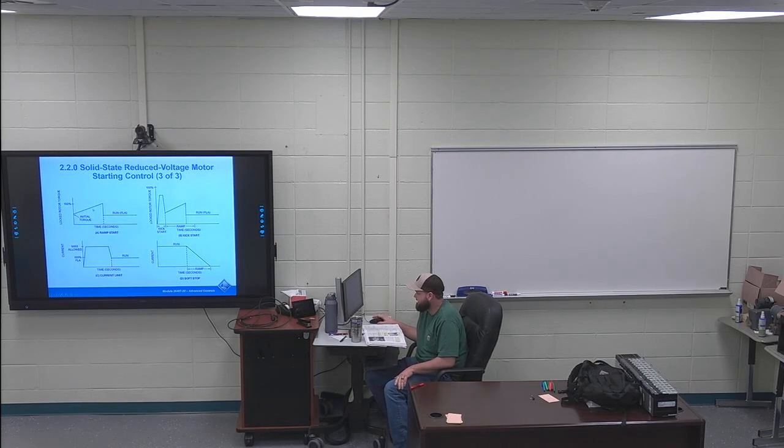Next bullet point, the kick start. So this is figure B, first sentence of that is highlighted. Kick start, shown in figure 19B, provides initial boost of current to the motor to help break free the motor and start the motor. So you're going to have a spike in amperage to help get this motor going. So where you have a large amount of locked rotor torque, you're going to use this kick start.